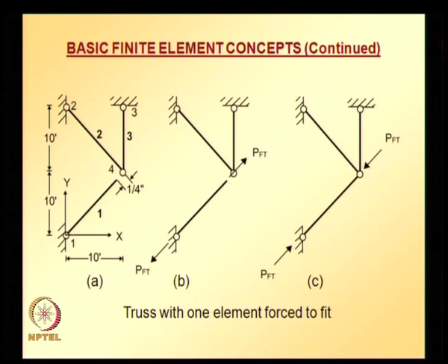So, figure B shows that actually the truss member which is short will be by some means stretched. So, it will be under tensile force, and this member in turn will exert an equal and opposite force which is shown in figure C. So, this member is actually going to exert a force as shown in figure C on the structure.